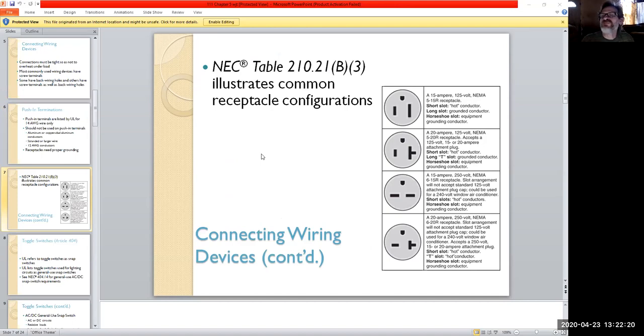So the very top one is your very typical standard NEMA, the National Equipment Manufacturers Association, who decide the voltage ranges, and also the spades you have on plug-in styles. Spades used to be of equal size, but on all the newer stuff, pretty much from about 75 on, the spades are different. One end is larger and the other is smaller, so you can't crisscross the hot and neutral, which is a good thing.